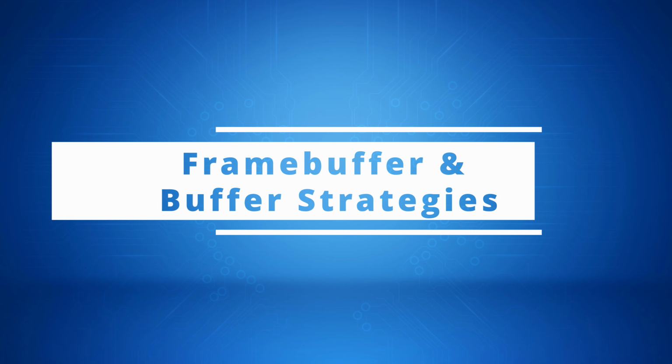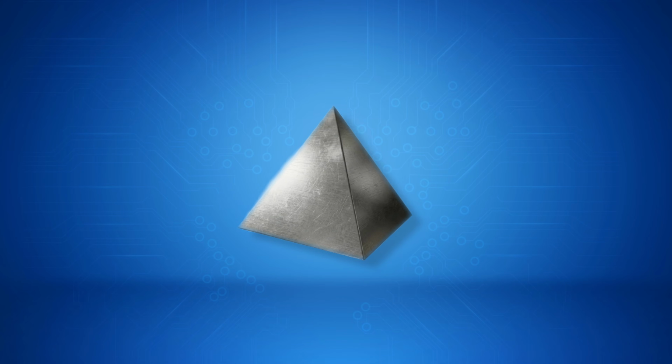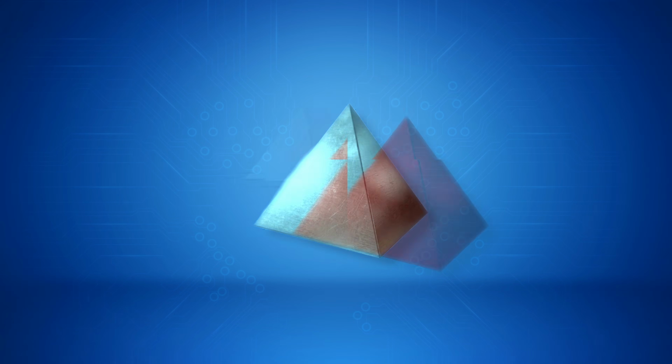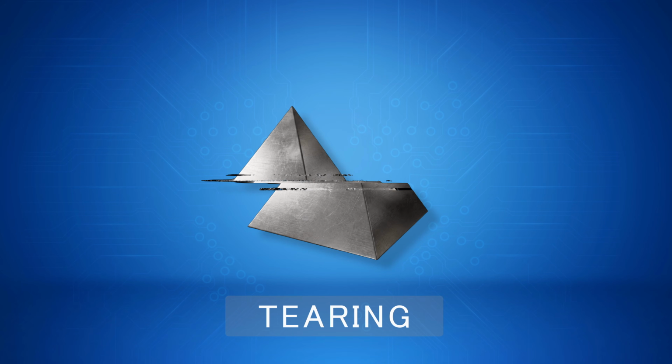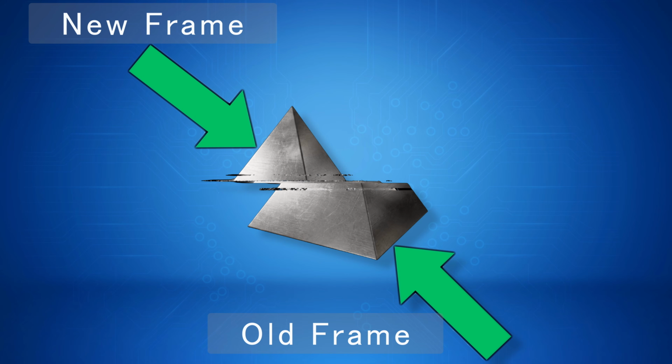So now that our compositor has a final 2D frame ready to go, we have to show it. The simplest way would be to have one frame buffer the GPU writes to, and the monitor scanout engine reads from it at the same time. This causes a huge, ugly problem called tearing. Tearing is what happens when the monitor reads the buffer while the GPU is still writing to it. The monitor ends up showing the bottom half of the old frame and the top half of the new one, creating a visible tear in the image.